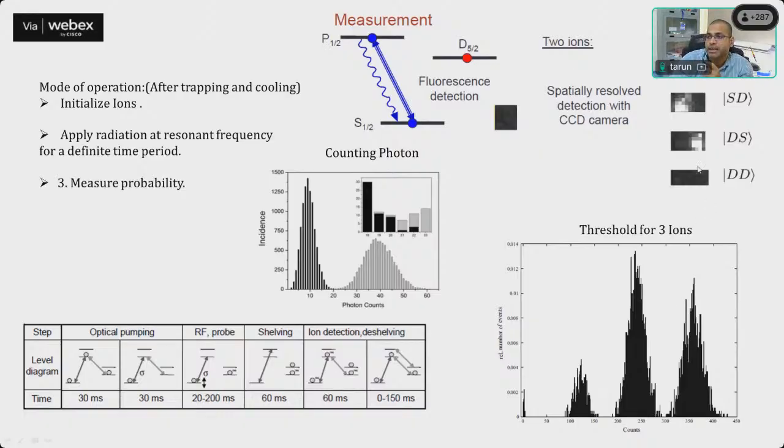Now, this is on the C schedule. Now, how are you going to check it? Because if you want to count the photon, then you have to use a photomultiplier tube, which usually counts photons. You have to give some threshold. Here in the middle figure, you can see where I'm counting photons. The signal is this one on the right side, from 20 to 60, and from 0 to 20 is the background count, that is the noise. Now the important thing is that you have to identify the threshold. Otherwise, you are going to miss some real photon counts. So that is one of the discrepancies.